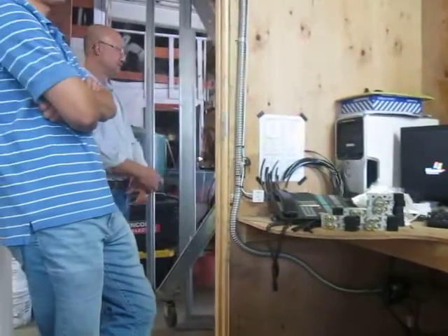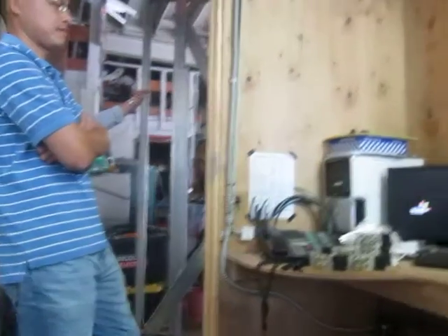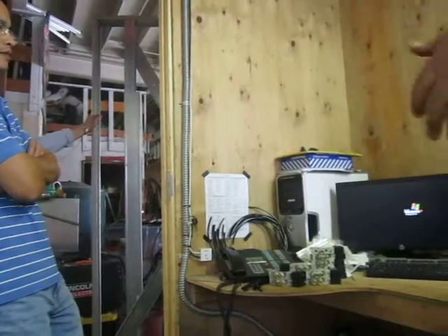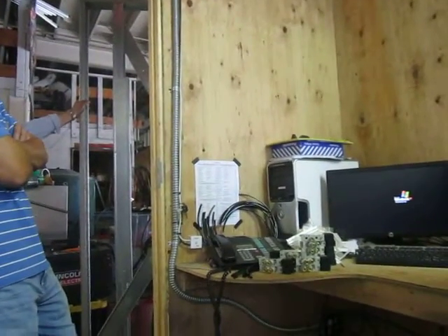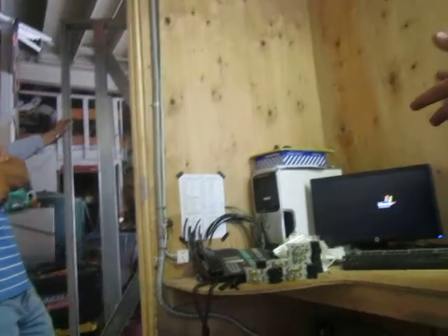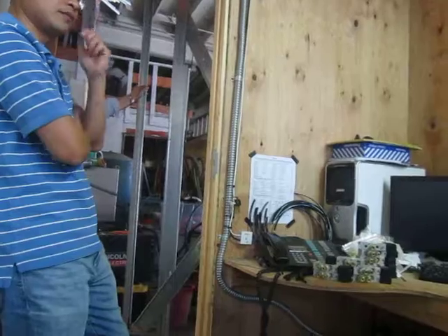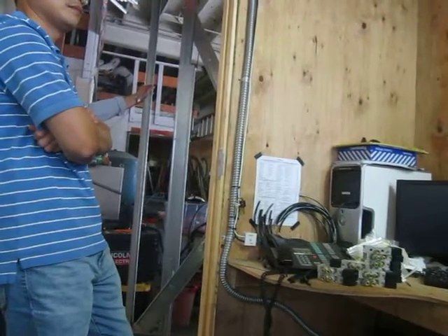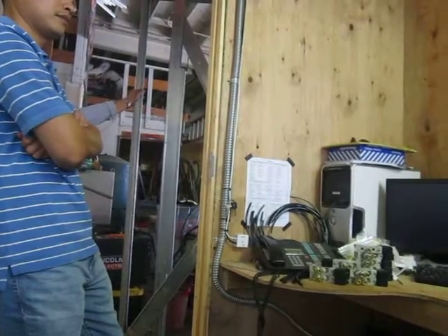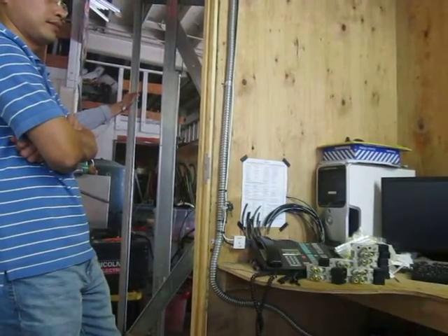Yeah, 100,000. Dual flush toilets have to be cycled, just flushing them on, off, on, off. One of the standards for the soft components of toilets, the flappers, the valves, the fill valve, all that stuff, is that you have to raise the flapper up and flush it like 50,000 times. So that's what the application is for these: just to do the hard cyclical testing on a component, just movement testing.